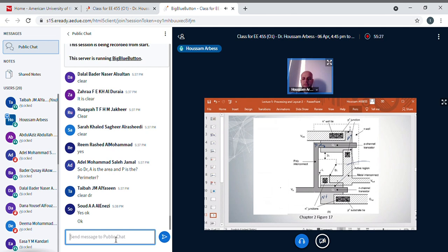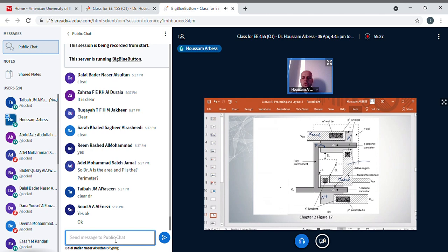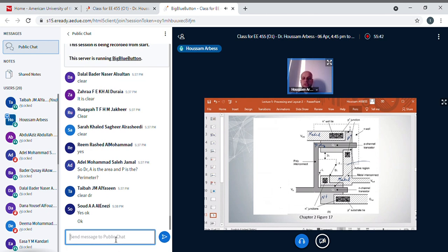So here I have metal, and metal here. Correct? Then I have also the dashed area here, which is N-well. Then you have the contacts here. They are squared, and inside there is a cross. Correct?